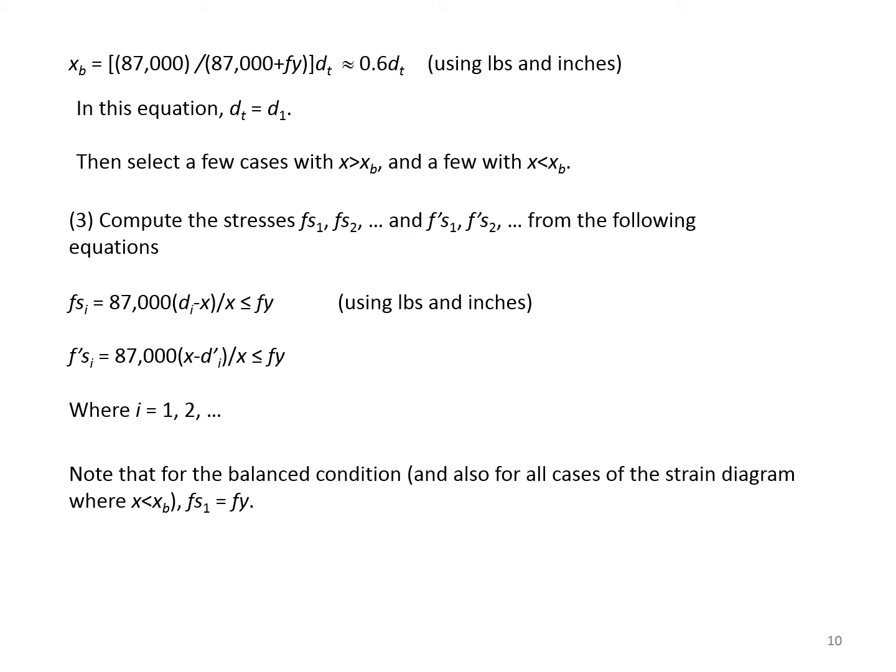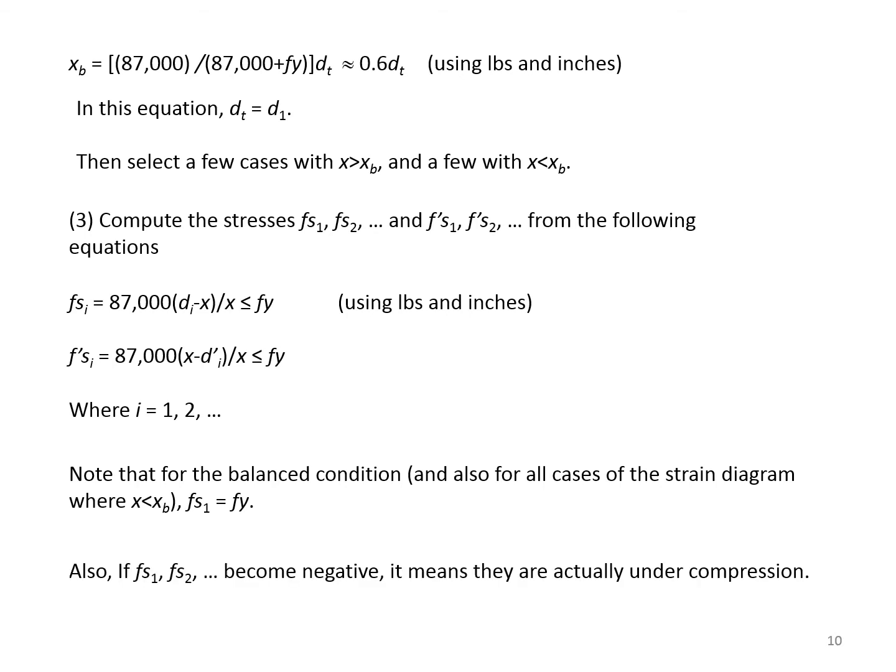Note that for the balance condition and also for all cases of the strain diagram where x is smaller than xp, Fs1 is always equal to Fy. Also, if Fs1 and Fs2, etc. become negative, it means they are actually under compression.